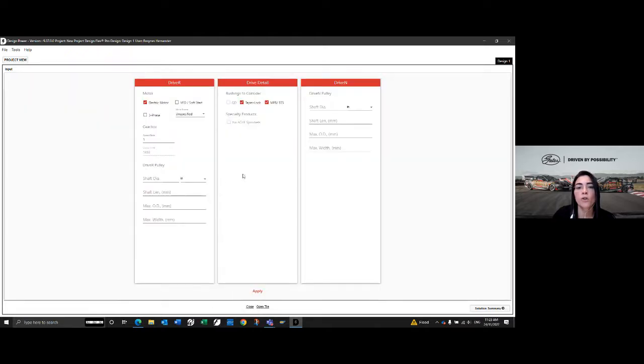All right. So if you see on the bottom part, there is an option that says more options. If you click on more options, you will have some more information you can put in. If you have all this information, it is better for you to do the selection. If the application has a gearbox, you can put the gearbox ratio, and then automatically it will calculate your RPM and adjust it on your driver.